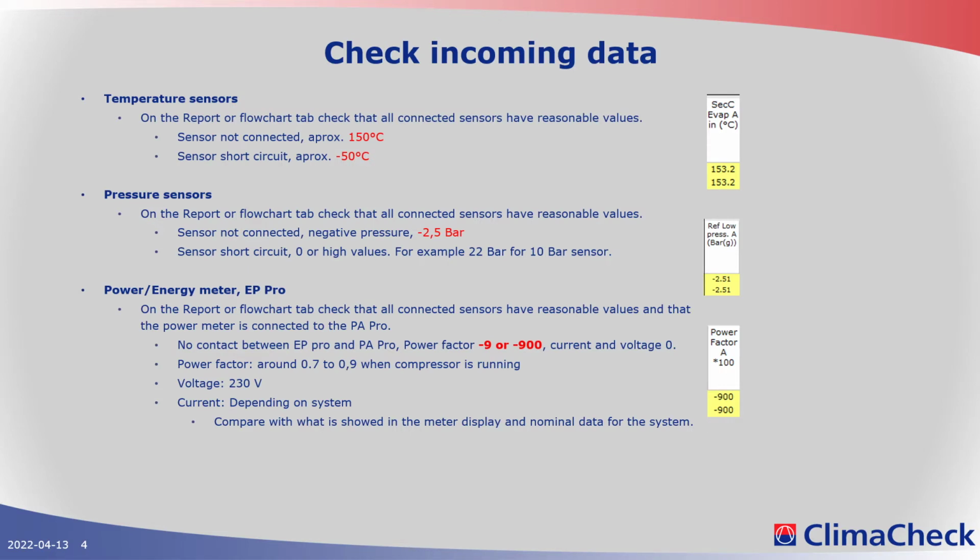So always consider that there can be something wrong with the measurement. Make sure that you don't waste time collecting a lot of data when there is a problem with your sensors, or you have missed applying something correctly, or there is some misconnection, so you put one temperature sensor and plugged it in, and then by mistake it was not in the right contact.